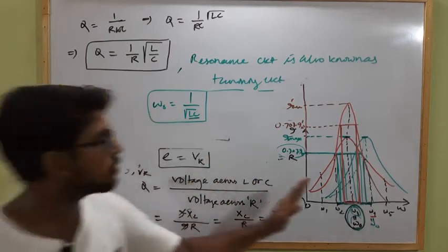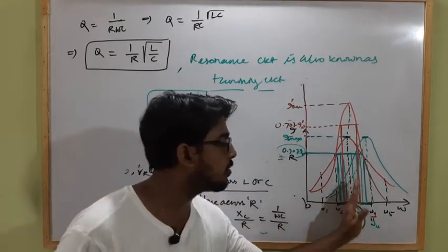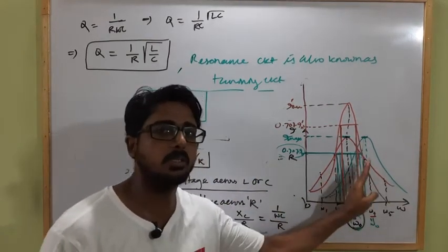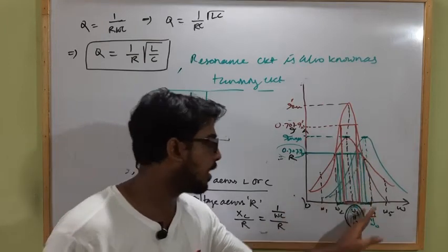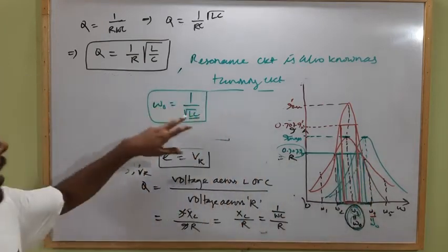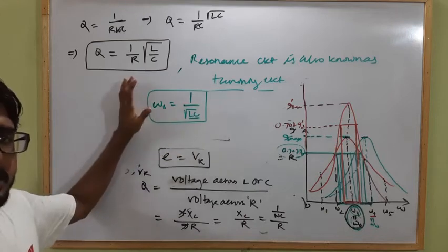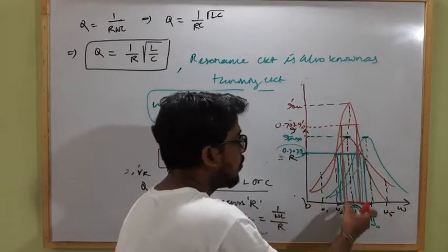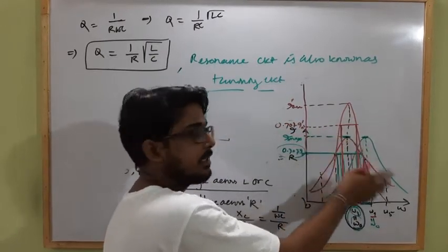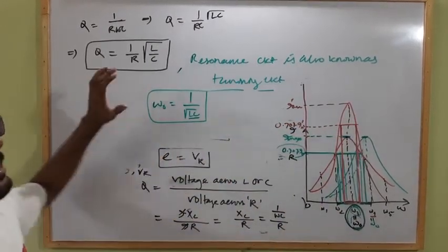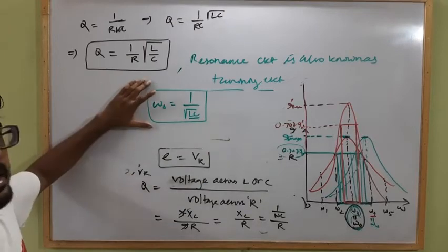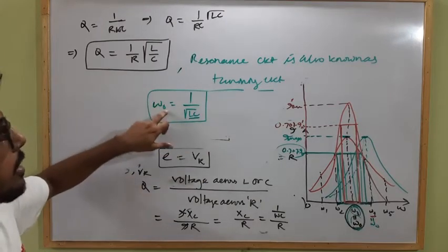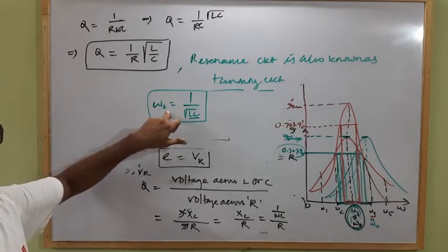So when I want to switch from one frequency to another or one channel to another in our television, we have to change the value of capacitance or inductance of the LCR circuit. But if we want to get more clarity in a given channel, then we have to change the resistance of the LCR circuit for that particular resonance frequency.